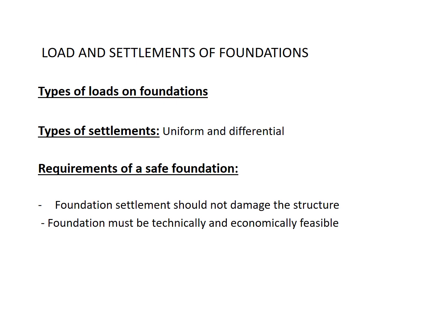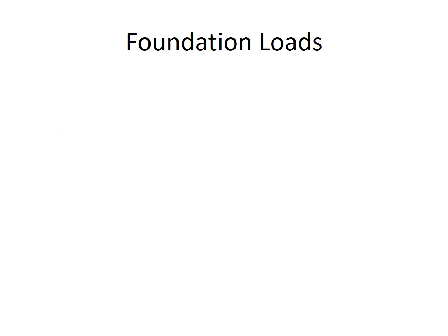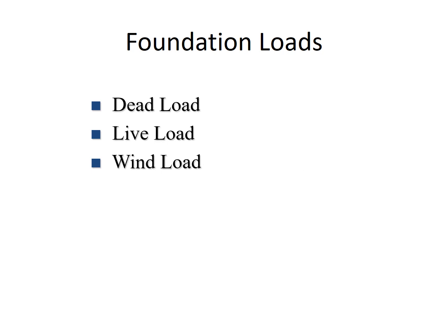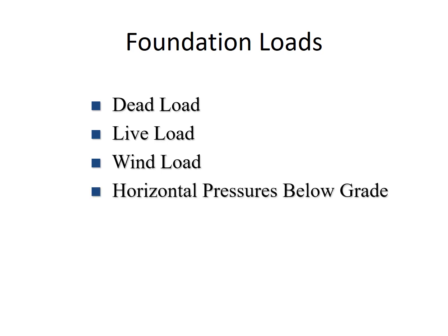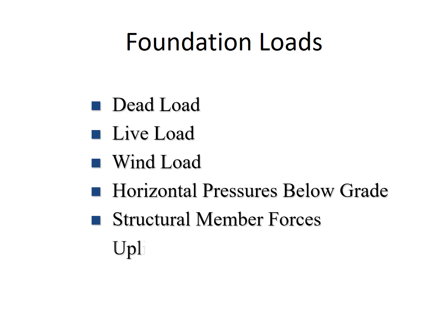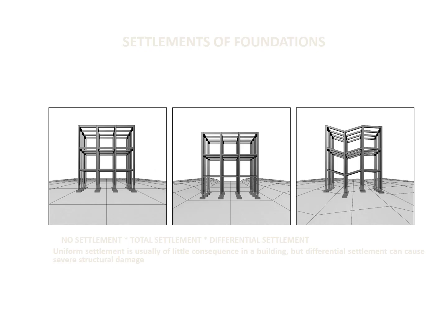building. And the requirements of a safe foundation, well, foundation systems safe against settlements that would lead to collapse need to be in place, foundation settlements should not damage the structure, and the foundation must be technically and economically feasible at the same time. So a little bit about foundation loads: the dead load, live load, and the wind load, along with the horizontal pressures, grade, structural member forces, and uplift, along with the earthquake or seismic conditions.